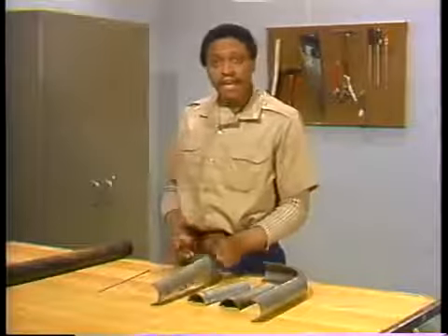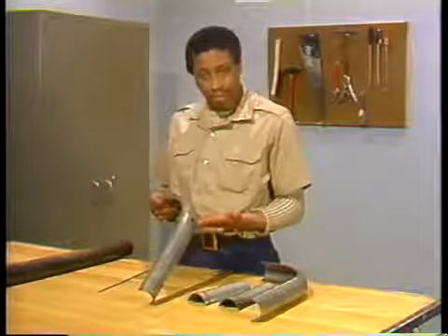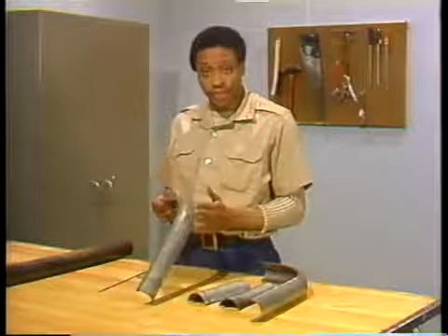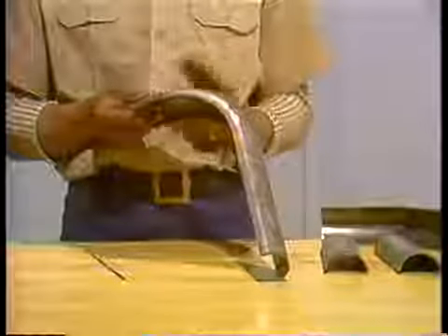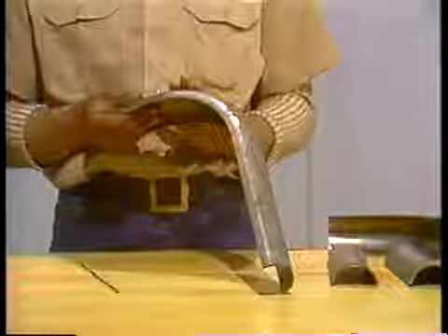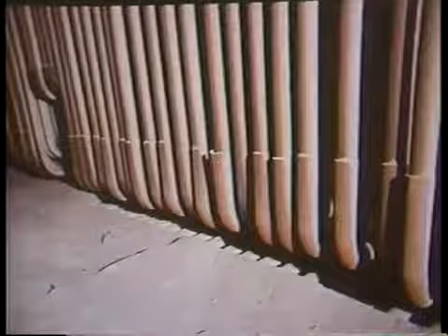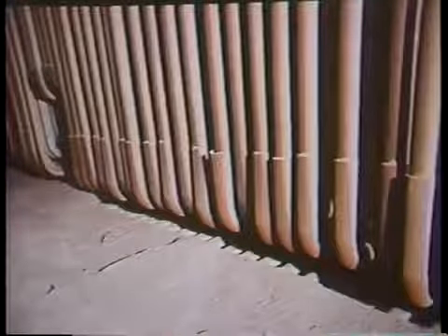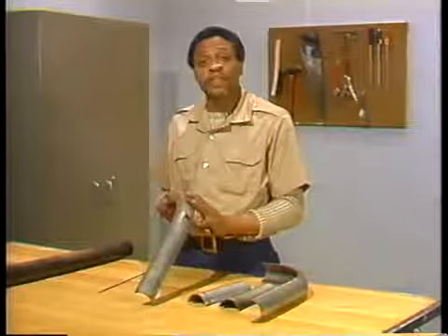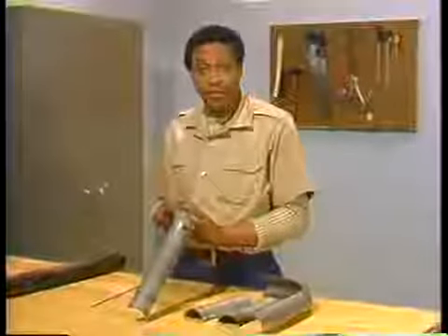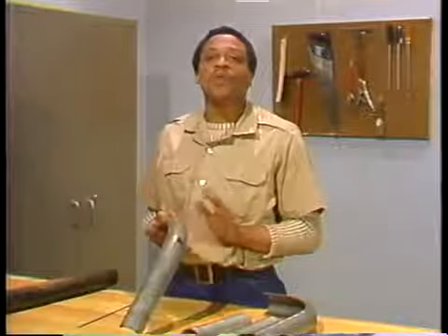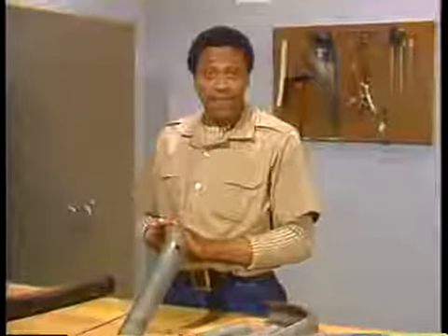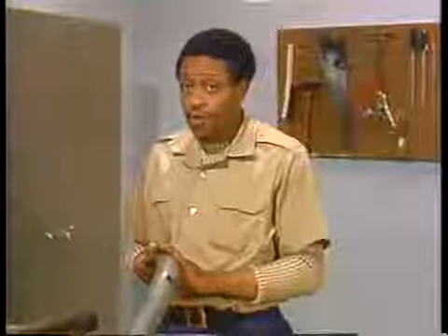If tubes are thinned only from erosion on the outside of the tubes, a tube shield is sometimes used instead of a clad patch. A tube shield is a metal plate, usually made of stainless steel, that is bent to fit over a tube. It is put on the side that is subject to thinning and then tack welded or clamped in place. The tube shield is effective in preventing continuing thinning from erosion on the outside of the tube. A tube shield is easy to install and requires little, if any, welding. However, it's not effective against thinning caused by corrosion, and it does not reinforce the tube like cladding does.